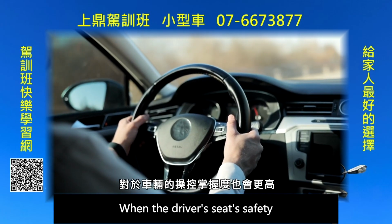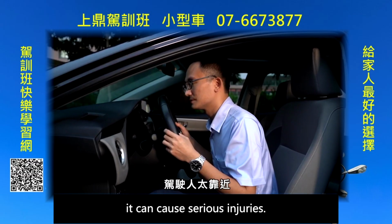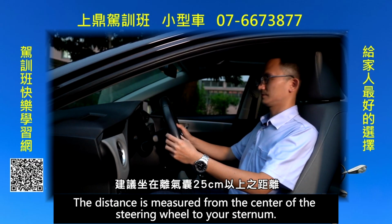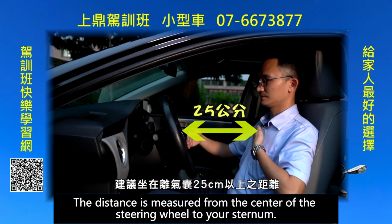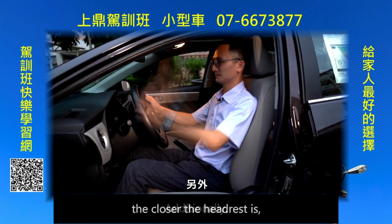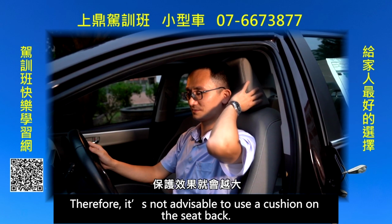When the driver's airbag inflates, if the driver is too close, it can cause serious injuries. It is recommended to sit at least 25 centimeters away from the airbag. The distance is measured from the center of the steering wheel to your sternum. Additionally, the closer the headrest is, the better head protection you will have. Therefore, it's not advisable to use a cushion on the seat back.